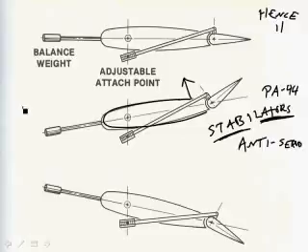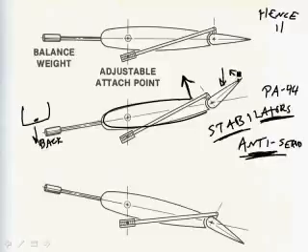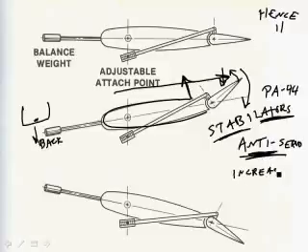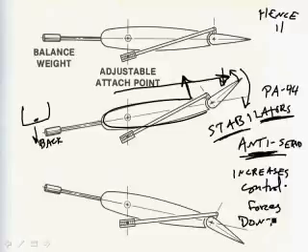If we move the yoke, if we pull the yoke back, that's going to make the stabilator move up. The anti-servo tab is going to move farther in the same direction, which of course now the slipstream hitting it is going to tend to try to push it back to neutral. So effectively, an anti-servo tab increases the cockpit control forces needed so that you don't accidentally over-control.